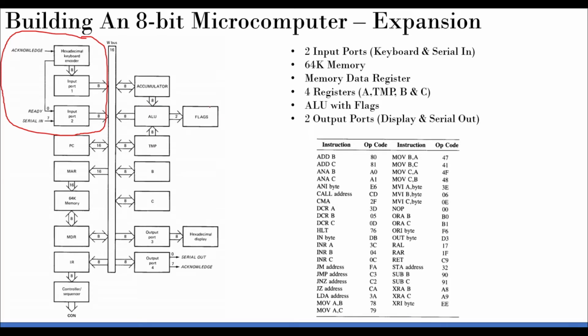And then of course the ALU is there, and then of course there is an option to flag, for example, if your addition is overflowing. Okay, so your carry bit is coming, then it's an overflow, and then of course you need to give that input or that sort of warning to the user, right? So that's typically done using flags. You might have also used so many flags in your C program, for example. So similar concept, but that's again registers, right? In this case, maybe it's 2 bits, so we can consider this as 2 flip-flops.